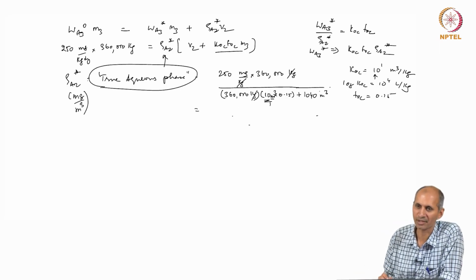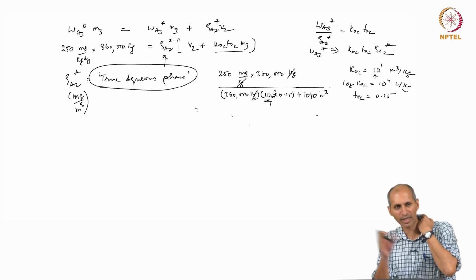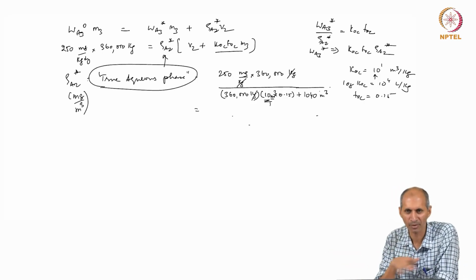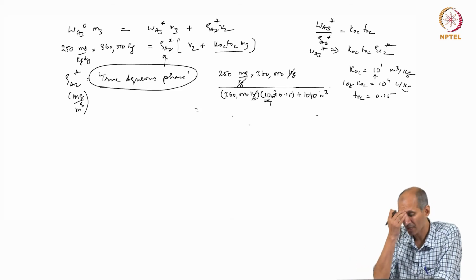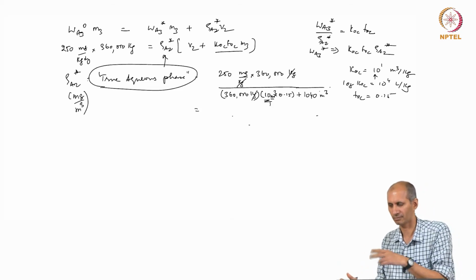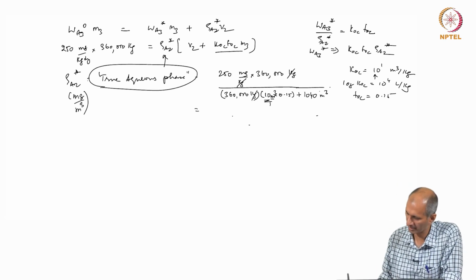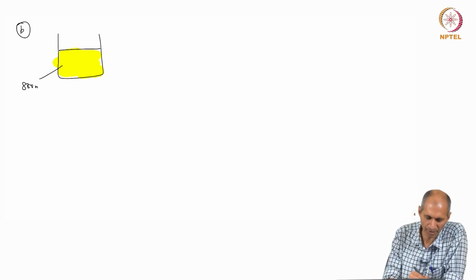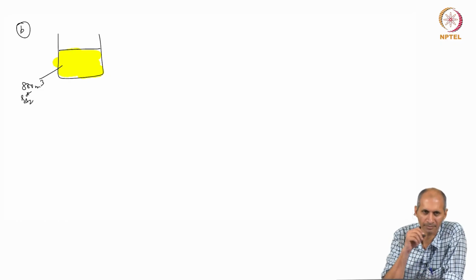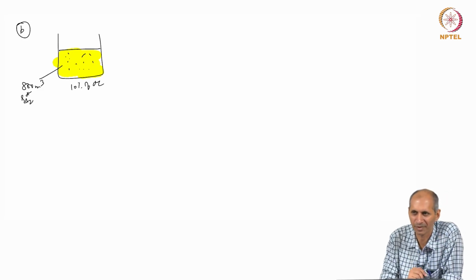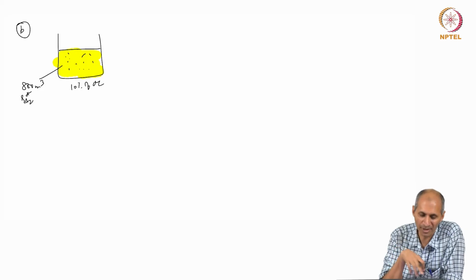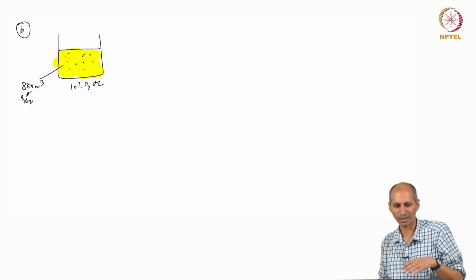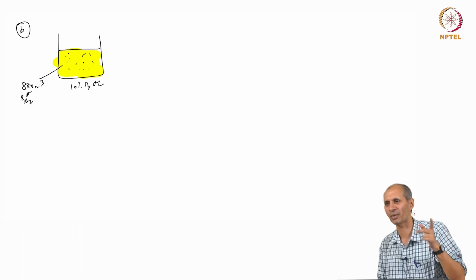But what we are doing now is, after separation, we are taking out that 800 and going back into a different chamber. We are retaining the original pore water, we are letting it settle down to its original capacity, and we are pulling out all the 800 into the next one. This is 800 meter cubed of rho A2 star, but it also contains 10% of the organic carbon that was originally there in the other one. Now here we are still not exposed to water. Now here is where I am exposing it to air and I am asking what will be the transfer there.